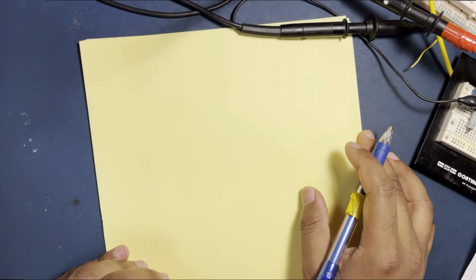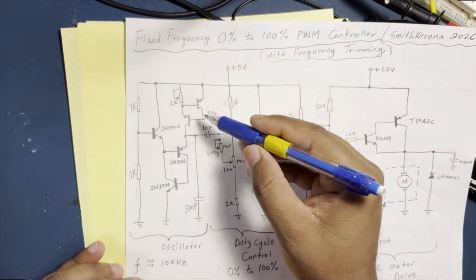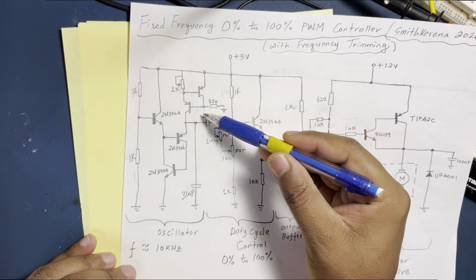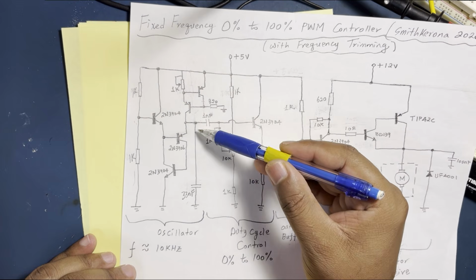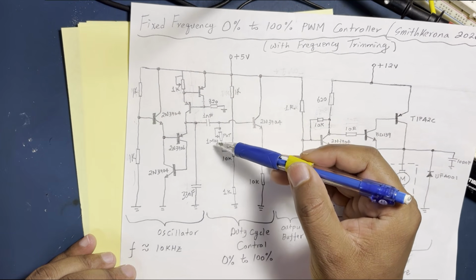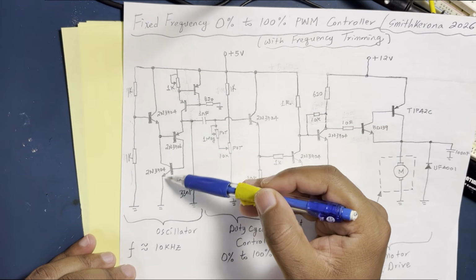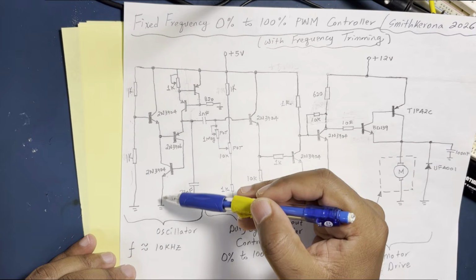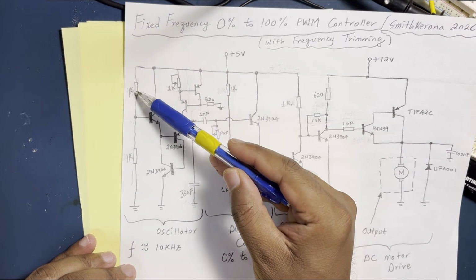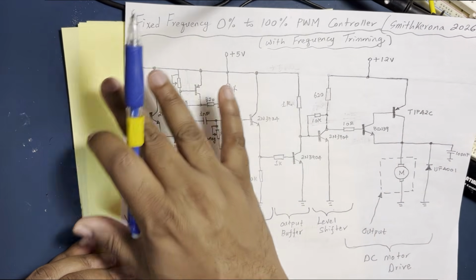So, as indicated, the oscillator section is made up of a current source, which charges a capacitor in a linear fashion, and when it reaches a certain voltage, it gets reset by a switch, which I described in the previous section as back-to-back PNP and NPN transistors connected. And the threshold is determined by this resistor divider. Basically, that's what we said. So now let's go in detail into how we design this.